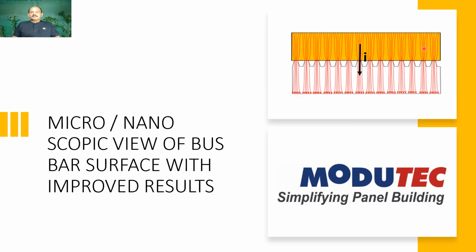See, this is a flat surface, which doesn't have any mountain-like surfaces on these flat bus bars. If you see like this, the distribution is happening evenly on the joint. So the current carrying capacity will also increase. So whatever calculations we have done for sizing of the bus bar, all these things will be ensured if you go for this type of surface.